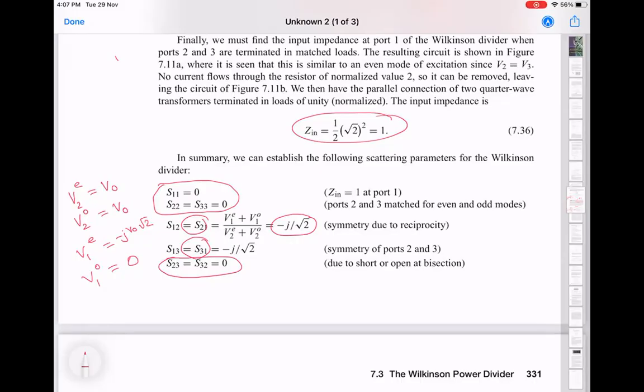Okay, so wait, is Microwave Office set up? Okay, let's try that. Even odd mode needs symmetry, and for a circuit without symmetry, this will not work. You will have to find something different to do. But most circuits will have some axis of symmetry where you can do this. We will take a quick look at some of those.